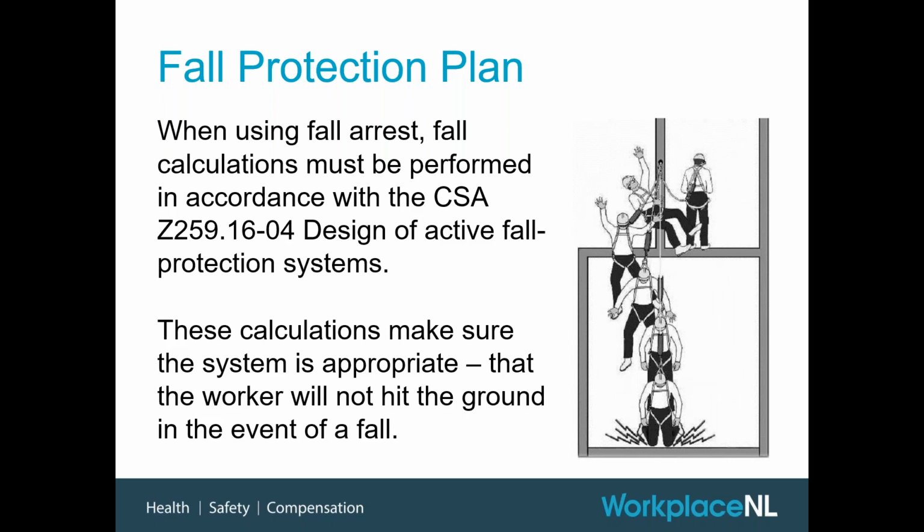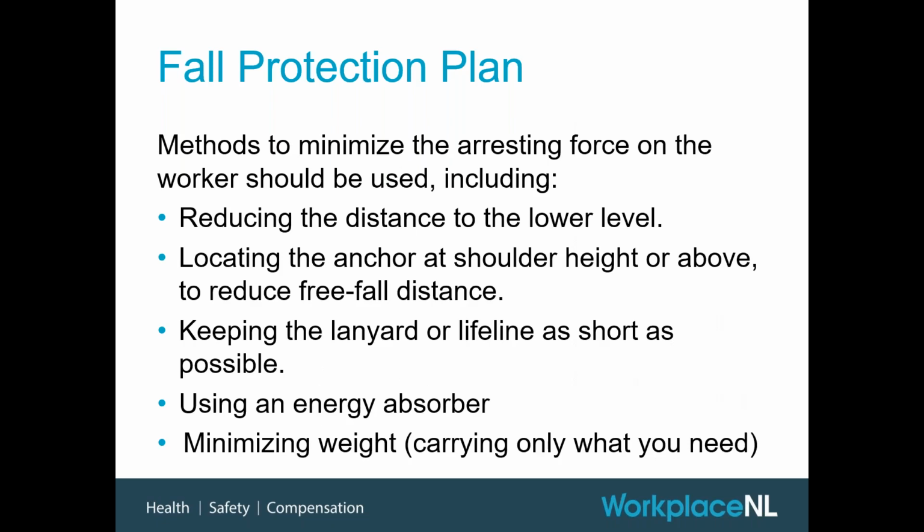These systems are meant to be set up so the person does not hit the ground with any part of themselves, and there really should be a bit of a safety factor, a bit of extra room for which they would dangle. And again, that's where this element of rescue comes into play, because you've got someone who's been suspended. They're dangling in the air, and now they need a means to get down from there as soon as possible. Again, because there are some circulatory illnesses that can come about when you're left in suspension for a long period of time.